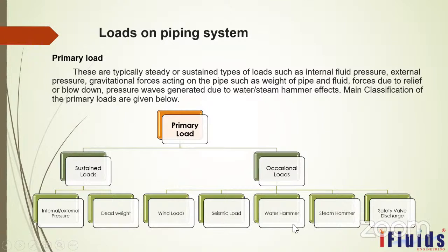And then water hammering, steam hammering, both are quite similar. You may have already heard about water hammering. Whenever there is a sudden stoppage or sudden flow in a pipe, it will cause a sudden shock. That is called water hammering. Sometimes it may create a noise also inside the pipe. Those kinds of shock have to be taken care of by the piping support. And then steam hammering, as you know, when the steam condenses, a partial vacuum will be created. Those kinds of shock also have to be taken care of by the piping support.